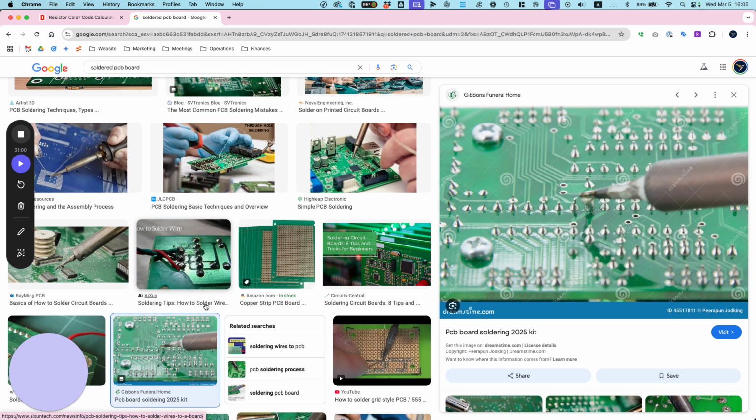So I'm gonna continue doing the other ones, but let me just show you how to properly solder. So I'm gonna take this one. Now this has been clipped, so we can't really just rely on the short and the long. If you had a new one, you can rely on the short and the long leads to know which side is which. But if you look on the inside, do you see the shape? It has like a slot, and the slot is slanted. So we want to make sure, I forgot which one's positive or negative. I think the right is the anode, which is the positive.